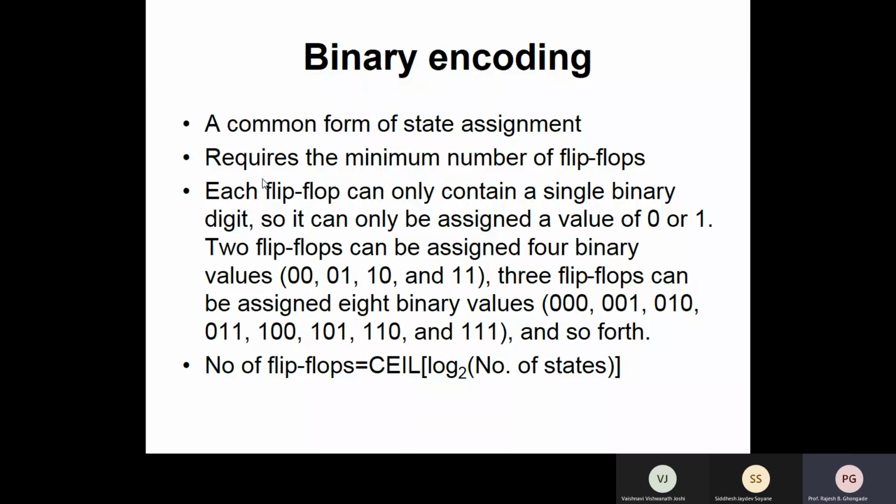So if you have n number of states, the number of flip-flops required is the ceiling, that is the upper value, of log to the base 2 of the number of states. Are you able to understand that? Yes, sir.